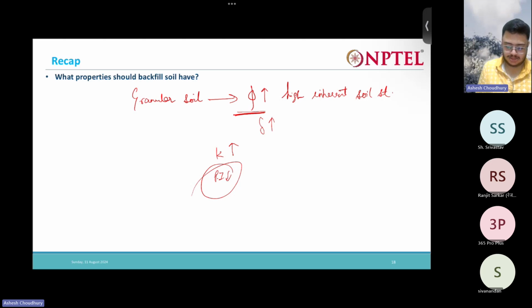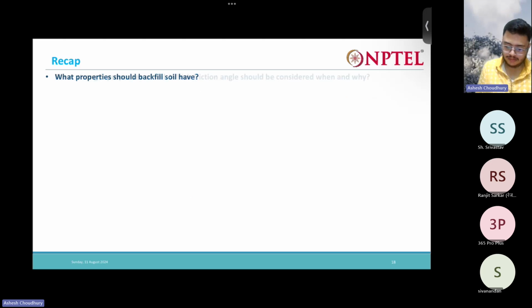Now tell me this. Which friction angle should be considered when and why? So generally what we do, we do direct shear test, right? From the direct shear test of the soil, we find out the friction angle of the soil, right? Okay. What is direct shear test?